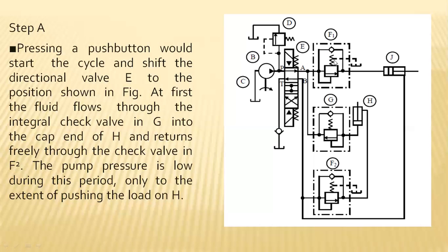So why has this sequence valve been arranged here? Is there any need of arranging so many sequence valves here or not? Indeed, it is to commence the work in parallel in two different activities. Clearly observe here, J is one cylinder and piston arrangement, and H is another cylinder and piston arrangement. Commonly, if you observe, there is an input passage. This is a forward stroke input line. Have a clear look.